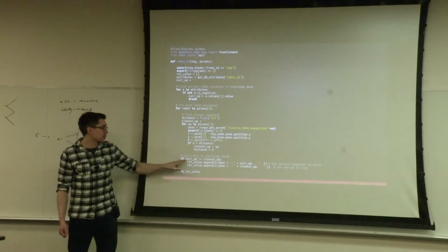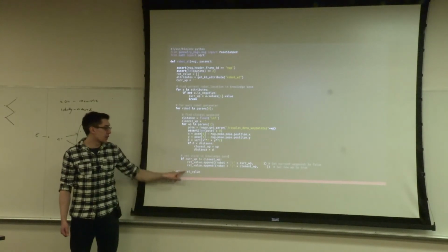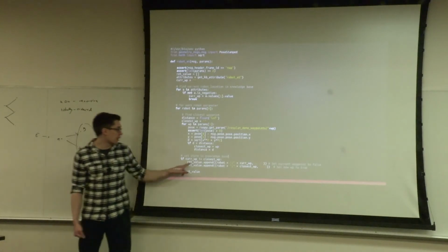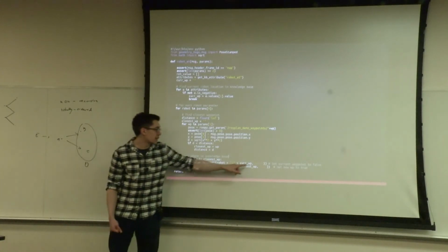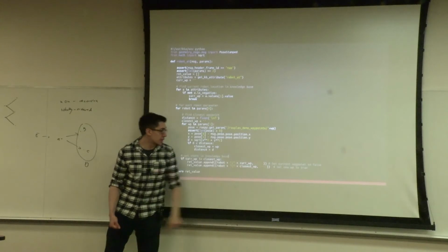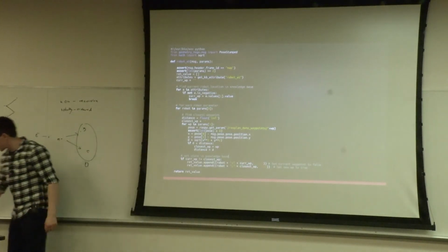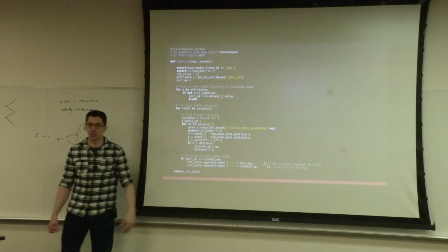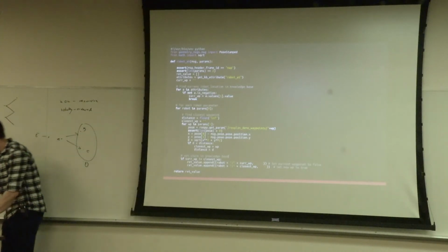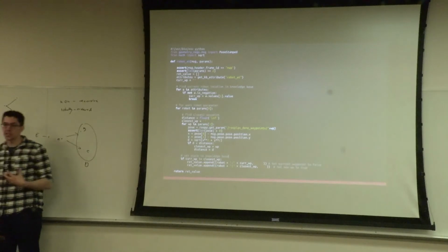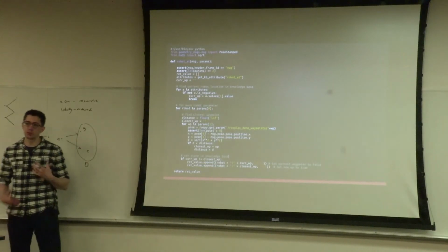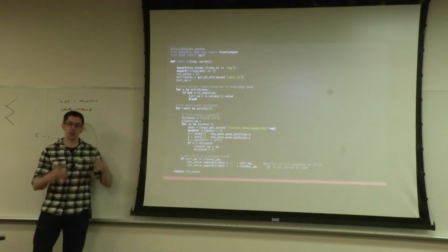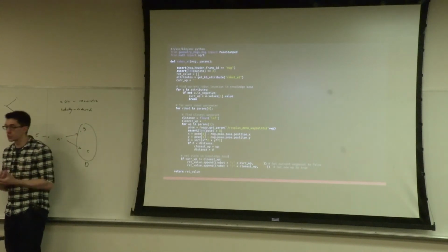Then if its current waypoint is not the closest one, it updates the knowledge base. It appends to the return value that this should be set to false and closest should be set to true. This is pretty flexible. You can write whatever you want to inside the Python script, and the integration effort it's saving you is having to write also the ROS subscriptions, the knowledge base updates, populating that knowledge item message. You can focus on just what's important.